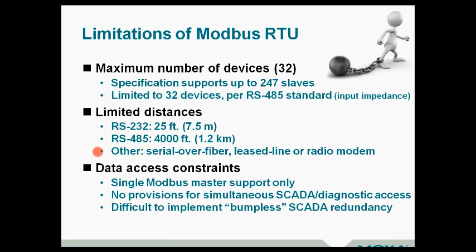And then lastly, because this has been architected for serial links, there's some real limitations on what you can do with your data. Maybe some of you face these same problems in what you do, right? Now I've got this data, how can I do more with that? How can I do more productive things and know more about my manufacturing process by sharing this data and looking at it more closely? The real limit is that when you have this single Modbus master limitation, whether it be a SCADA system or an OPC server, whatever it might be, you're really limited in what you can do.